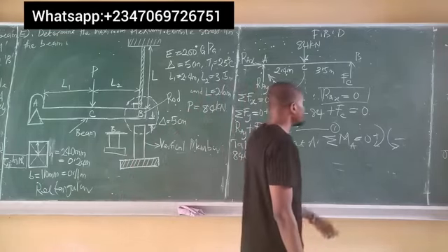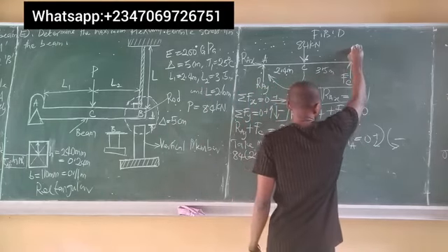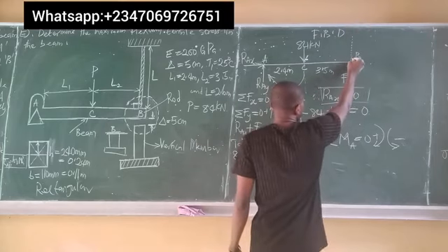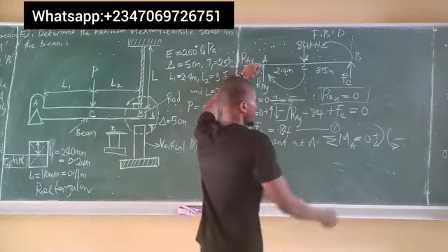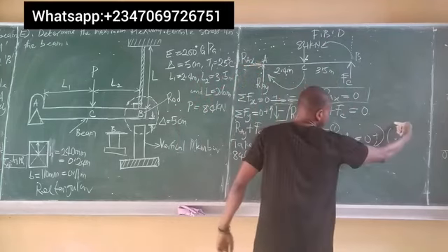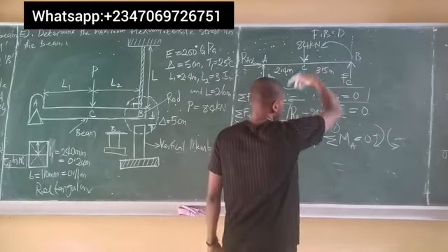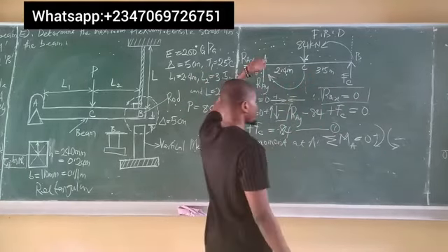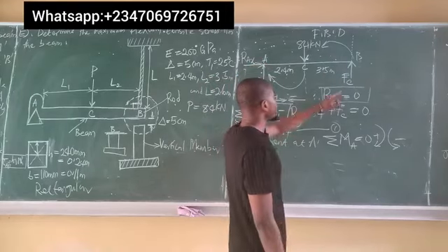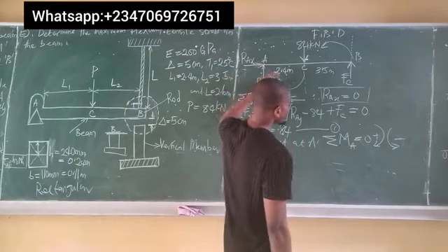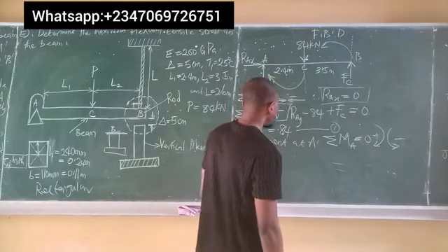Next, we have the cable force FC. This force is pointing upward, which means the line of action of this force goes up. That means this force will turn about in this direction to take moment at point A. And if you notice, this direction is anti-clockwise. We said let anti-clockwise mean negative. So the moment of this force about point A is a negative moment. And then the total distance it takes this force to get to point A becomes 3.5 plus 2.4, which is actually 5.9.